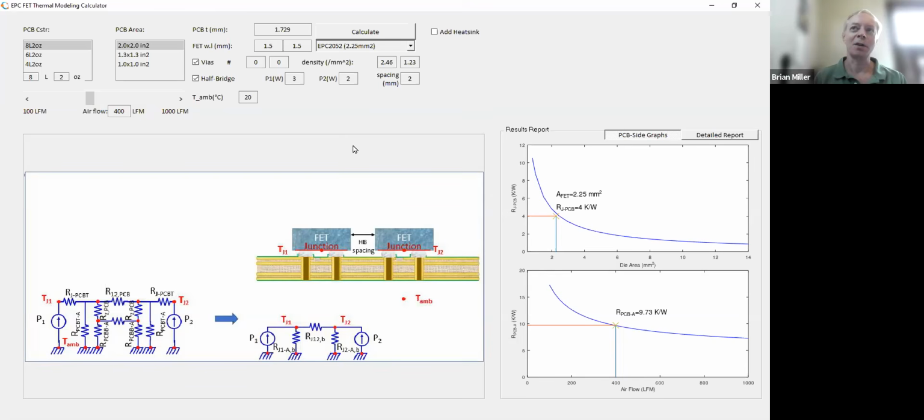On the other hand, we don't want to be overly pessimistic with the results and have a bigger heat sink than is really needed. It sounds like the question results from a design that had an overly optimistic board. But even there, a lot of the thermal information given in the data sheets, including EPC's, everybody's in the same boat, uses like 1 square inch of copper in a board to get the thermal resistance to air and so forth.